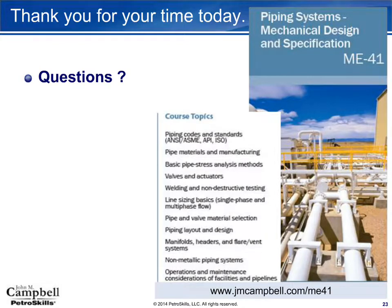Context is everything, and understanding if it's a process facility or a pipeline is going to be a big factor that needs to be addressed first. There are sections within both of the codes that identify that resonance within a piping system is a factor that needs to be considered. The code does not specify the means by which it needs to be addressed, just that it needs to be addressed.